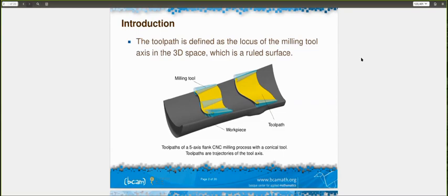When the tool traverses the toolpath, sometimes it is going faster and sometimes slower. This is generally because of the toolpath parameterization when it comes from a CAD model, for example, and the parameterization may cause kinematic unsmoothness. So we want to reparameterize the ruled surface to resolve the potential kinematic issues of the motion.